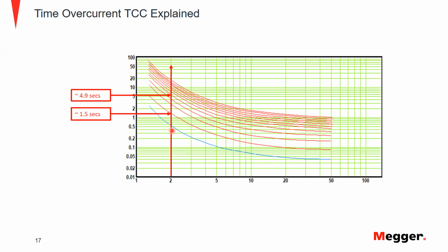I didn't draw this out, but let's say we had something at the 0.5 mark here and we wanted to keep it at 0.5, we would come all the way across. This first time dial would hit us at 2 times the current value, but then if we hit 0.5, we might not even get across it until we get a little bit after 3 times the current multiple.